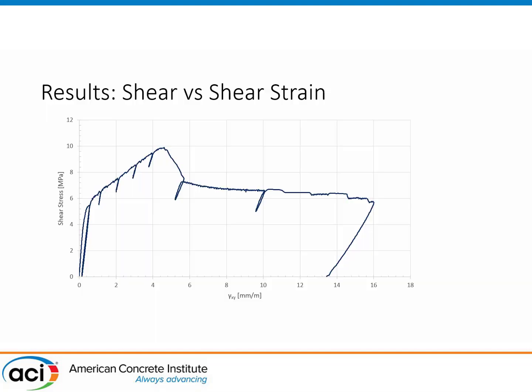Here's the behavior in terms of the shear stress versus shear strain. So initially it was linear elastic. You see we did an unloading cycle there and then proceeded to load up after cracking as progressive cracks got wider and more cracks formed. We were very surprised to see how linear it is after cracking. Normally we would expect to see nonlinearity in there somewhere. Instead, we did all this work to measure two slopes, but we're very excited because modeling two slopes is easy. And so surprisingly linear.